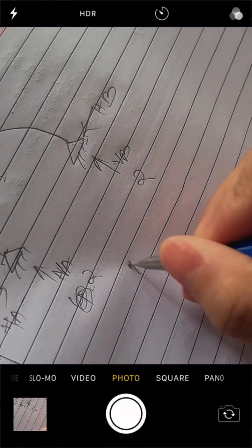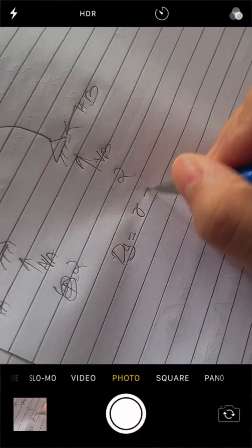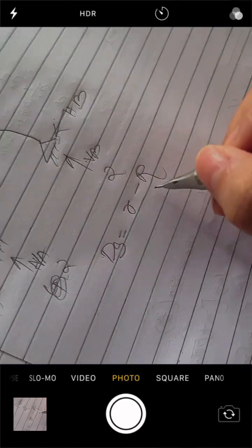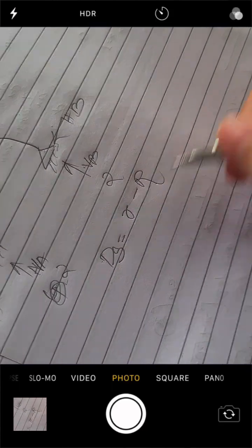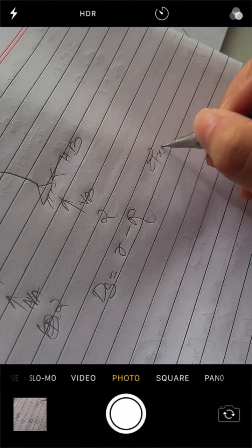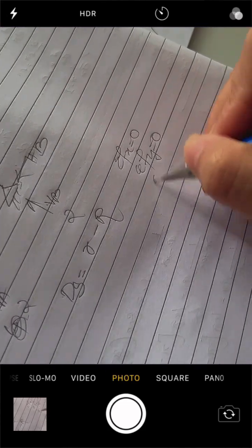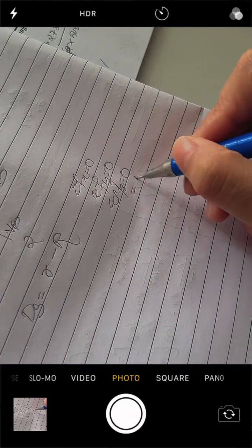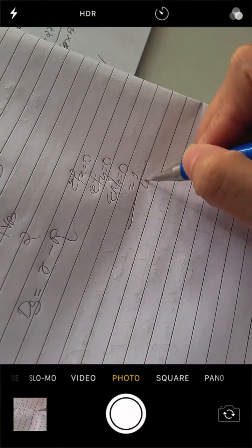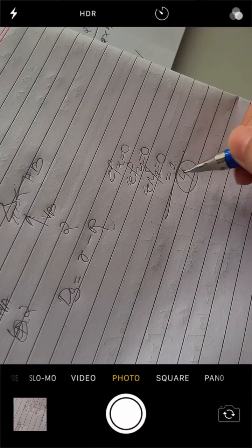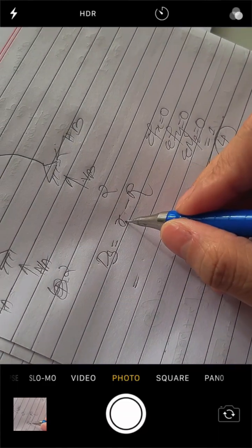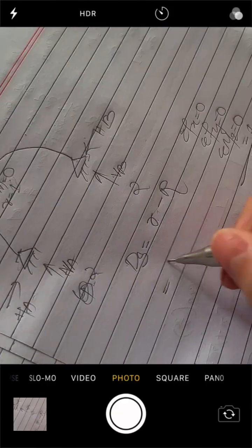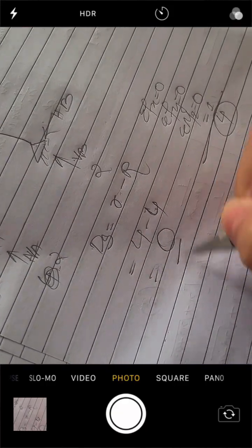And we know the degree of indeterminacy is r minus R. This r is my number of support reactions. This R is my number of equilibrium equations. We know that for equilibrium, summation Fx equals 0, summation Fy equals 0, summation Mz equals 0. For this internal hinge, there will be one extra equation generated. So therefore, we have 4 equilibrium equations. So therefore this r, the number of support reactions, is 1 plus 2, which is 4. 4 minus 4 is going to be 0.